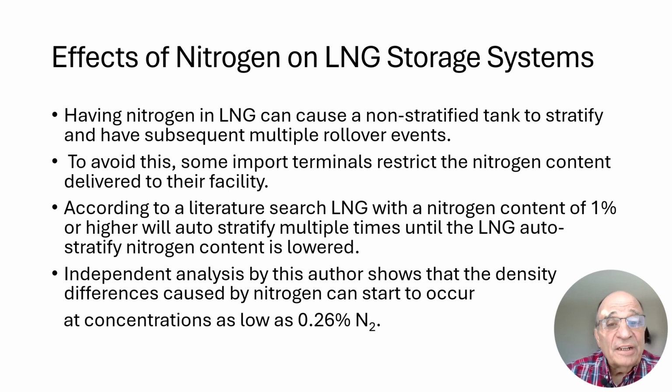Having nitrogen in your LNG can cause a non-stratified tank to auto-stratify, and then you can get subsequent rollovers. And as we mentioned earlier in other lessons, rollover is a serious event that can be hazardous as well as can discharge a significant amount of boil-off vapor to the atmosphere.